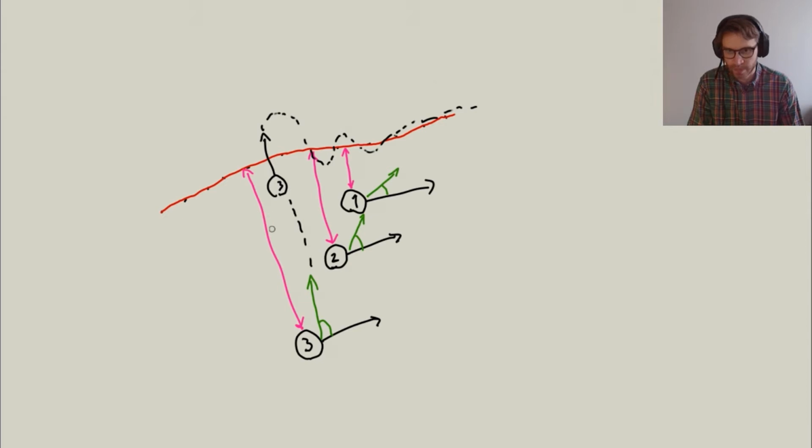So we can get rid of that by looking ahead into the path and not trying to get to the point that we're right next to, but get a little bit further. So this was cross-track error-based PID controller, or type of control.